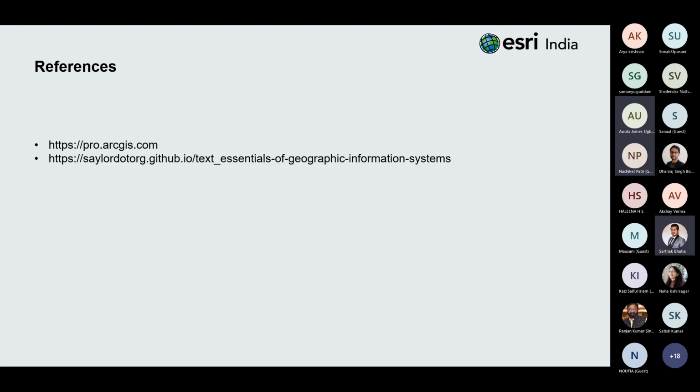So the requirement that you have, sir, we do not really have a corresponding tool for that, which can take 5 different attribute values and help you classify 5 different columns based upon the agriculture classification that you're talking about, for instance, or the land value classifications. The best way to build this will be to build a geoprocessing model, wherein each particular section appends a new field and calculates the value based upon intersection.